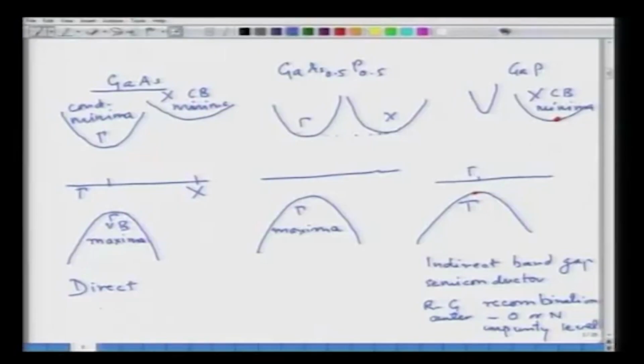And as we have seen, through some recombination process we can sometimes even use the indirect band gap semiconductor to get light. So, this is one way of trying to change the emission. One way of changing band gap is the composition, and III-V semiconductors are wonderful to allow this because they have complete solid solubility in each other. So, you can change composition and go all the way from 100% gallium to 100% indium or 100% aluminum, and change the band gap as well as the lattice parameter.